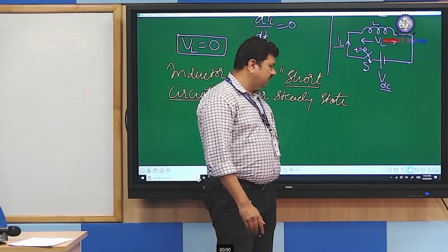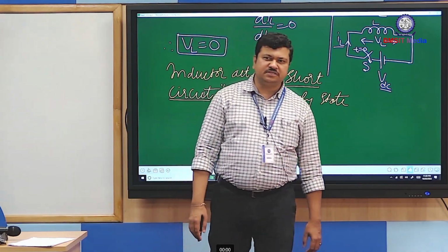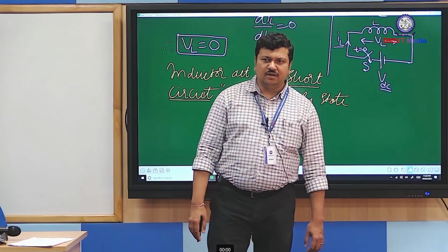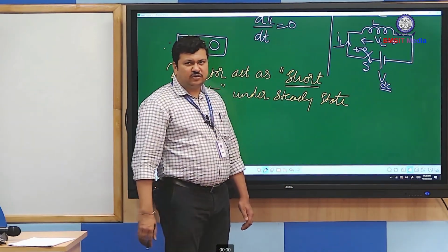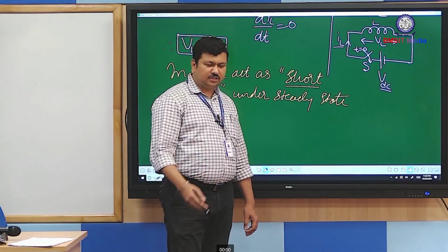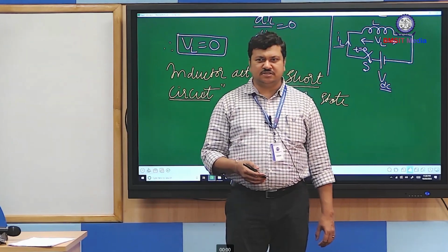So, that is why we generally say that transformers are never to be connected to DC, as the transformer windings are inductances directly connected to DC. It will create a large current flowing in the transformer winding and it will burn out. I think you might have heard this when you studied the fundamentals of electrical science.